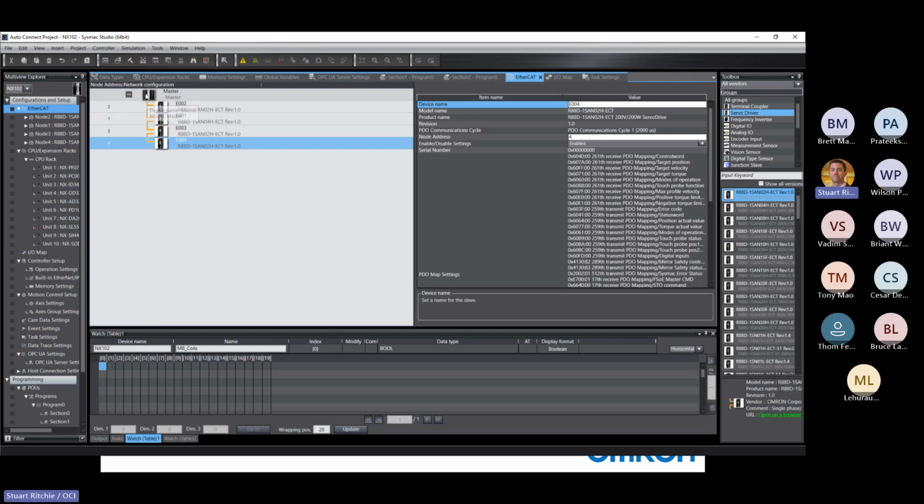With Ethernet IP, we would have to send a packet to each of these individually, often multiple packets, to get an update of their data. With EtherCAT, we basically send out one packet with all the data going to the nodes, and it passes through the daisy chain, dropping off that data at each device.